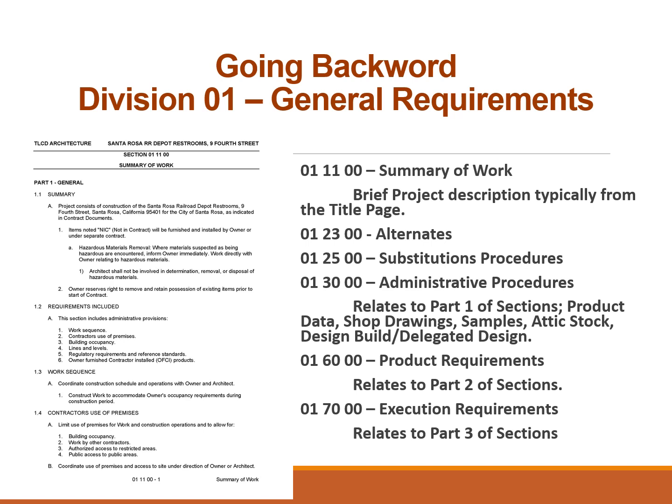I don't want to rely on the contractor and the subcontractor going back to Division 1 to see that the 5-year experience is required, because they might say, oh, I can use this product here instead of what you specified, where the reason they want to use it is they can use it and have anybody put it in. They don't have experience. And my own experience is, especially on the exterior of the building, if I'm going to have a joint sealant, I want it put in by people that know what they're doing.